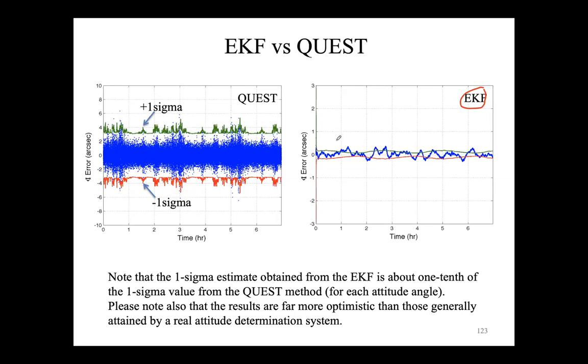So the gyroscope has a very nice effect on your estimation if your Q and R are well behaving. As I said, R is associated to the star trackers error, so it is usually well known. The problem is finding Q.